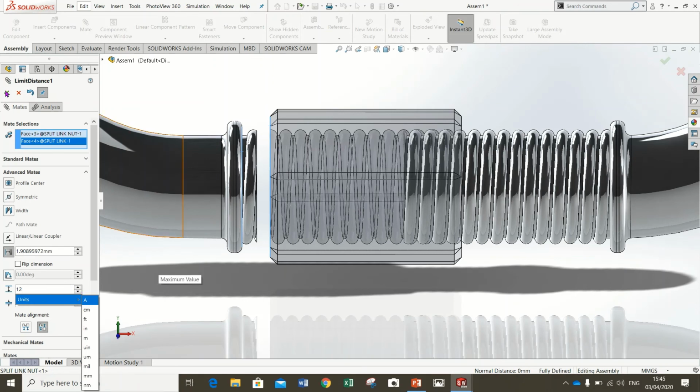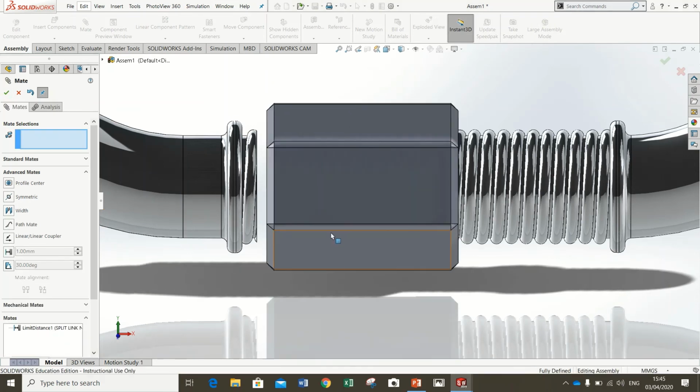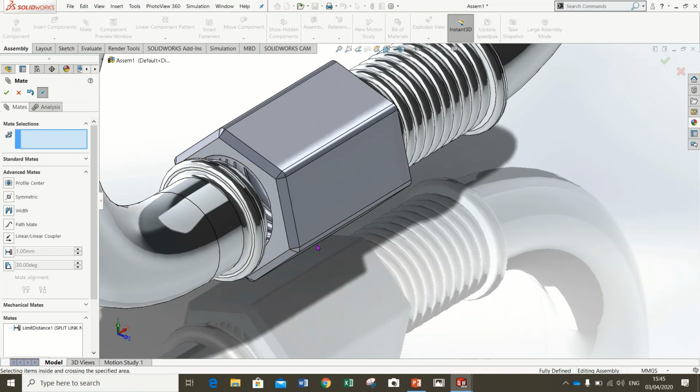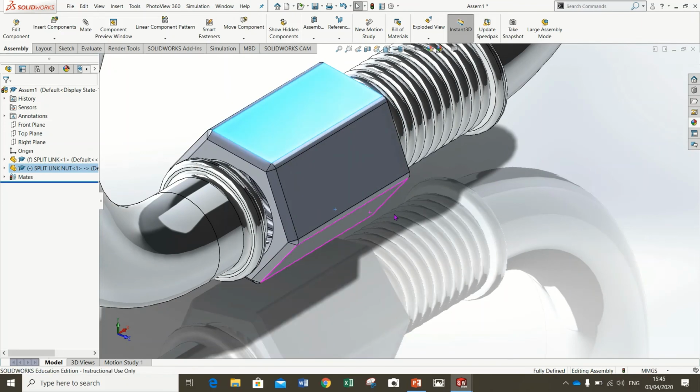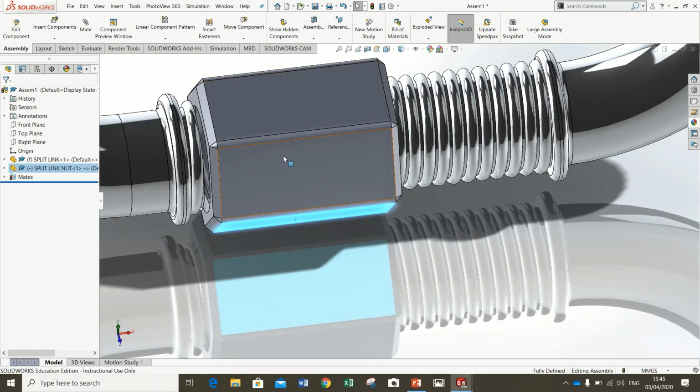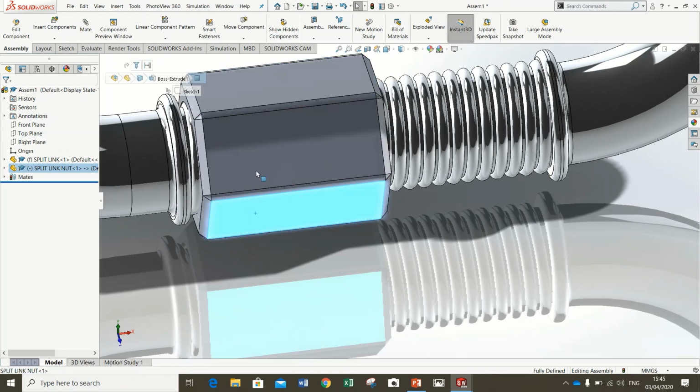Okay, so what that's going to do when I accept that, that will allow me to thread it. You'll see the difference now again. Now it's taken a long time obviously to thread this guy because it's such a fine thread on it. So the pitch of it, you could up the pitch of it, and you wouldn't have to be rotating that as much if you like to be less thread length on it.